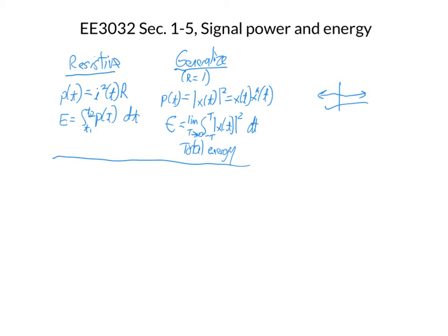So like, let's say another signal of great interest, just a simple sinusoid that goes on for eternity with the same magnitude and frequency. If I want to calculate the energy of that, it's going to go to infinity because I square it, so I have a non-negative quantity that I'm integrating over all time. And the power is changing. So we introduce this concept of average power.